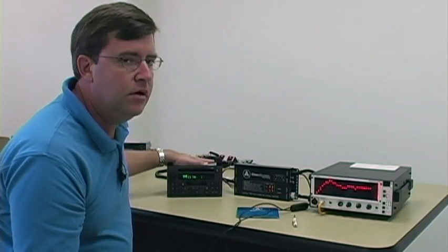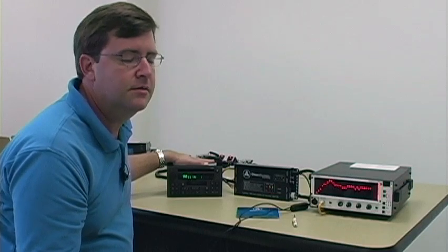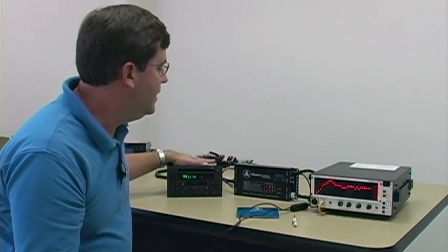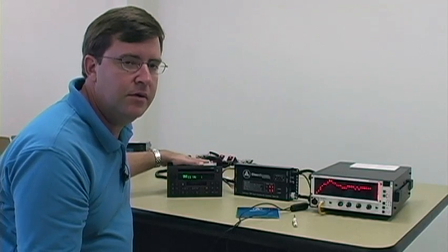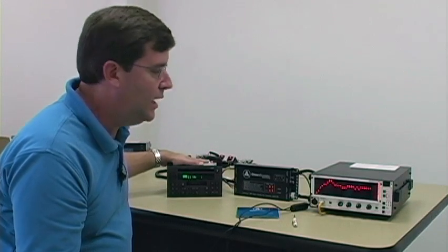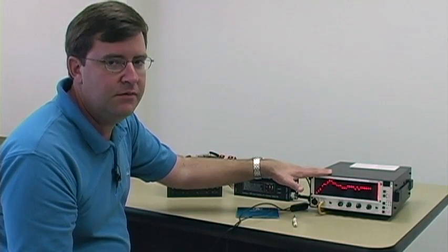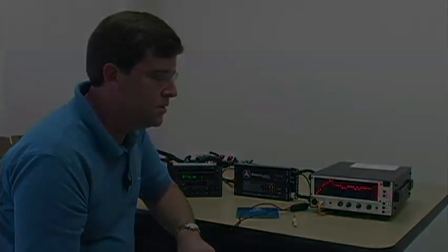There's something we haven't found in this system that is necessary in order to complete the full audio range. And what we haven't found is the fact that this head unit, as with many Ford premium systems, has a separate dedicated subwoofer output coming out of it. So by not grabbing that low frequency information that's on that subwoofer output and adding it to these front and rear signals, we're not able to achieve full range. So the next step we have to take is to apply a summing interface to do this.